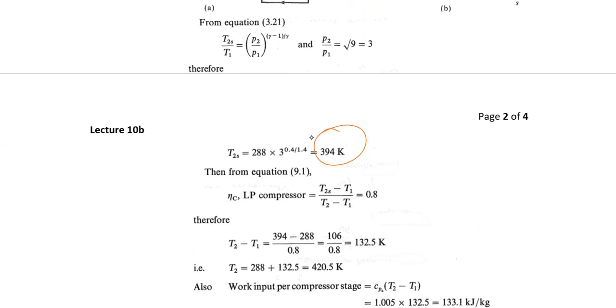So using this formula for the efficiency, isentropic efficiency, which is 84% for the compressor. The isentropic work done divided by the actual work done, which in terms of enthalpy would be Cp(T2s minus T1) divided by Cp(T2 minus T1). So Cp and Cp got cancelled. So you have got (T2s minus T1) divided by (T2 minus T1).